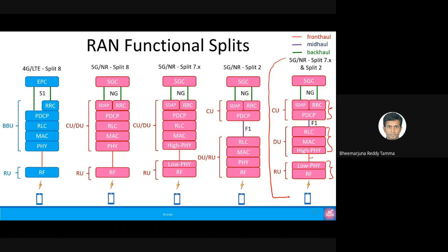The link between these two is called the fronthaul. Yeah, it is called fronthaul. The one between DU and CU is called the midhaul. This could be a microwave link or a fiber link, depending on the channel bandwidth at the base station. So we have to provision that amount of capacity on the transport network. It is like an optical network or WDM network or something. People use it to realize the connection between RUs and DUs and between DUs and the CU.